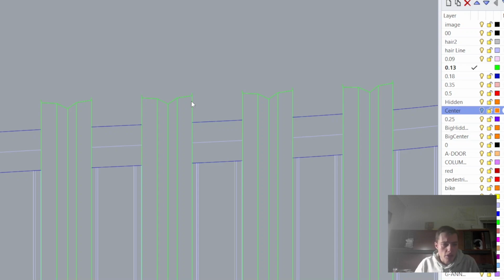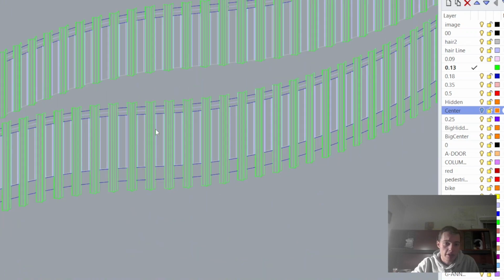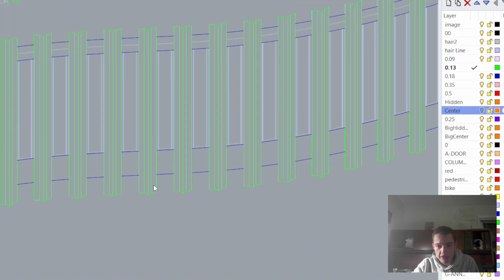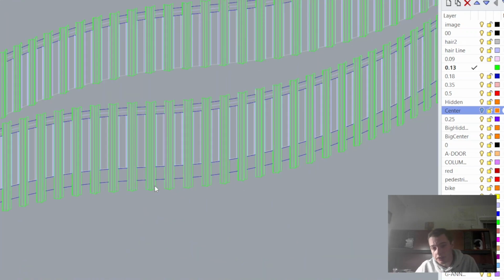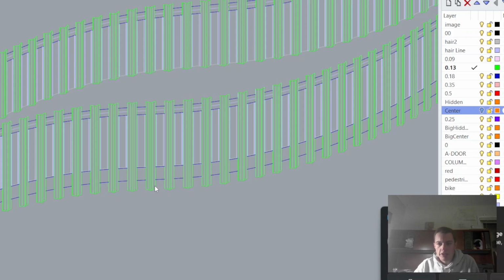And so I did the math to figure out how much load each one of these wall segments can support. It turns out it can support enough, about 275 kilonewtons was what I calculated there. In this case, buckling was the limiting factor.